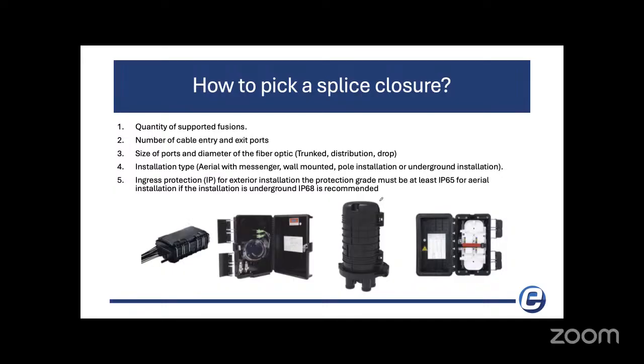And for other installation, we recommend for aerial at least IP65 and for underground IP68. IP68 mostly for the ingress of water. So it's very important when you're doing underground installations to go with IP68.